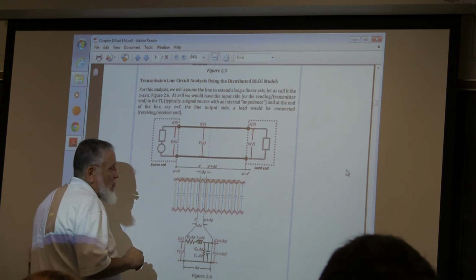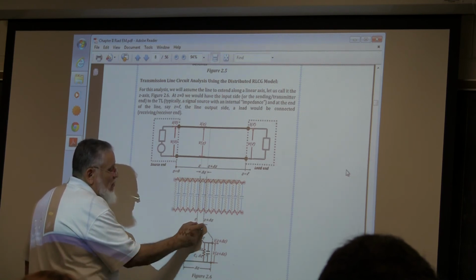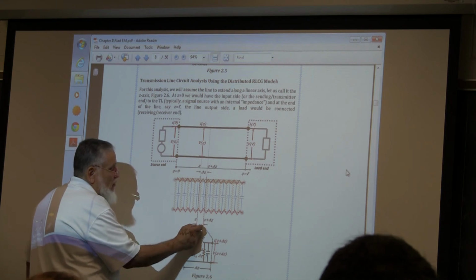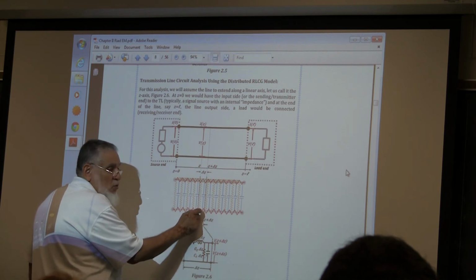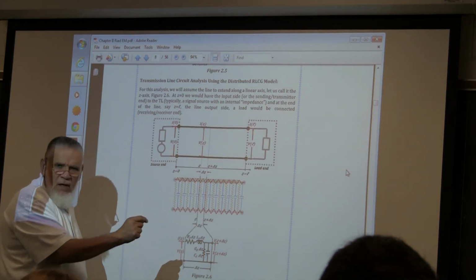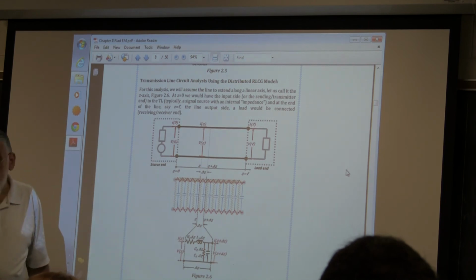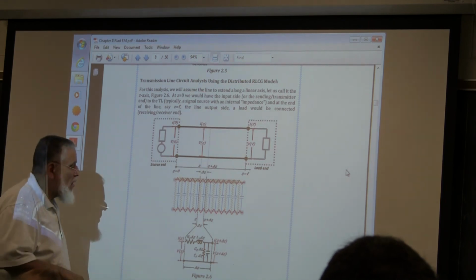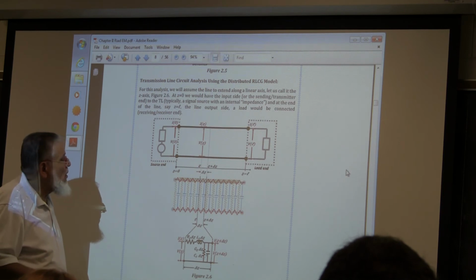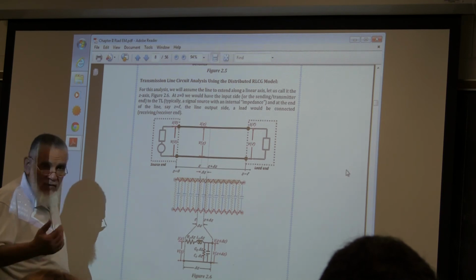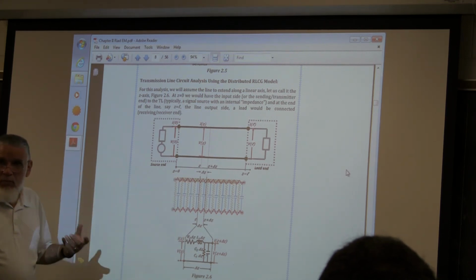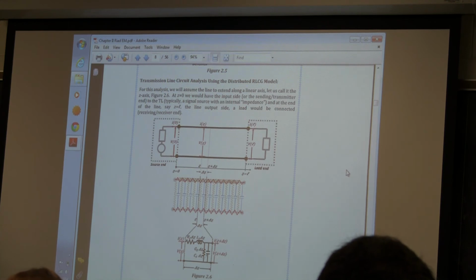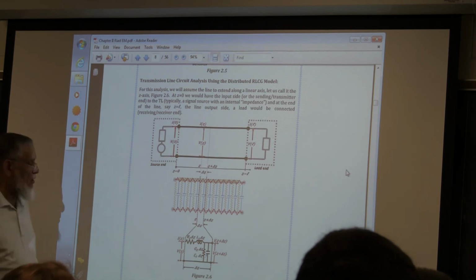for this frequency range. So what we do is we take an increment, hopefully small enough, delta z, and we look at the model for that. That delta z here is much, much too small compared to the wavelength. And in the limit, I'm going to take it to 0 anyway, so I will be covering a wider frequency range with that. The limitation in this analysis, like I said, is in coming up with those numbers for the particular frequency range. Converting the field solution into the RLCG model is the limitation here.